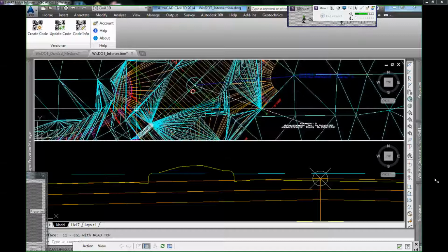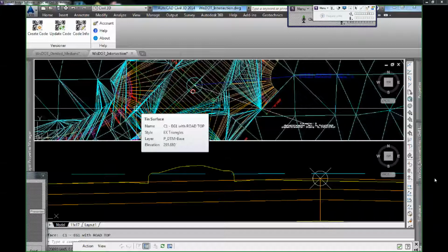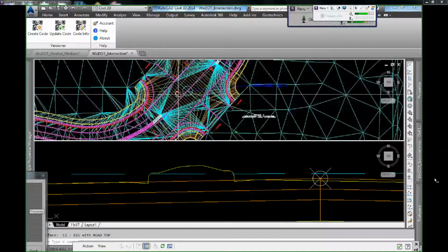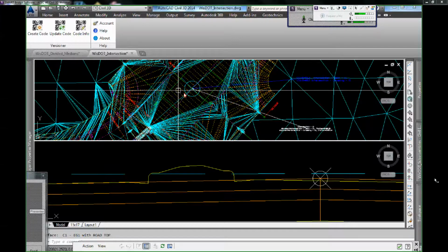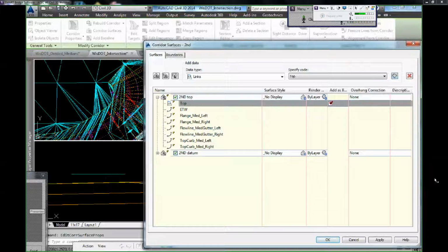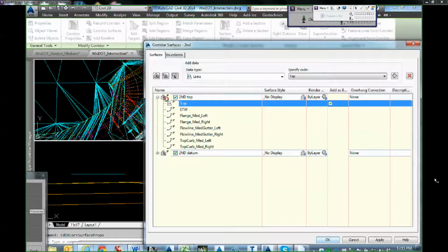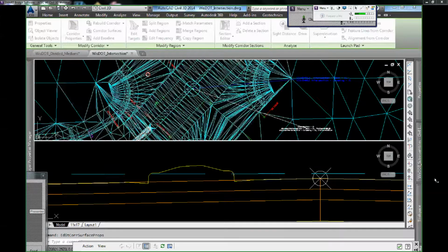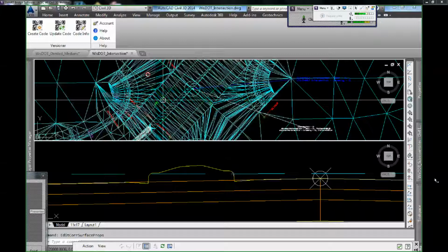So when you take the links out of the surface definition, that's why it's ignoring a bunch of stuff. See, if I was to go back in here and add the links and turn them into break lines, then that cures that. But then you run into other issues.